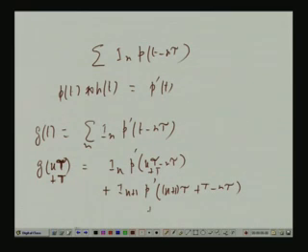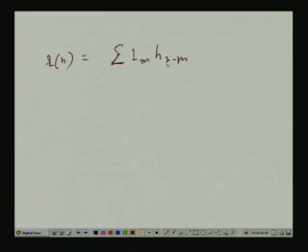Okay, that means you get a discrete time model, that if you sample it, what you get? The received sequence, say R n, is nothing but a convolution, that is, sum over m of I m times h n minus m.